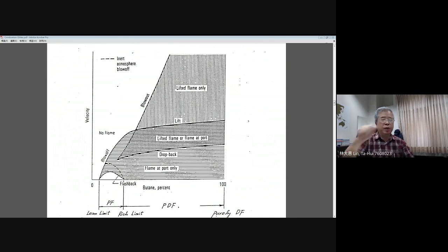That means that you produce a diffusion flame. Now you can think about, okay, we return to real conditions. The oxygen exists in the outer surrounding. Then for the rich case, especially in this region, you may have a diffusion flame existing accompanied with the rich premixed flame.